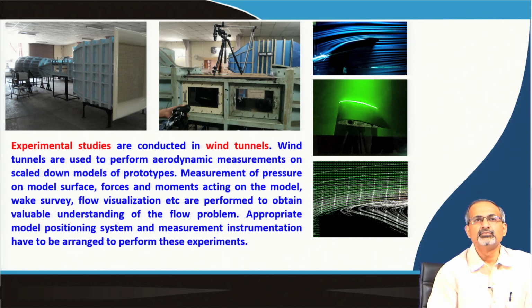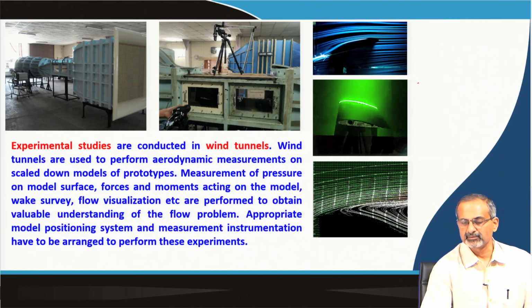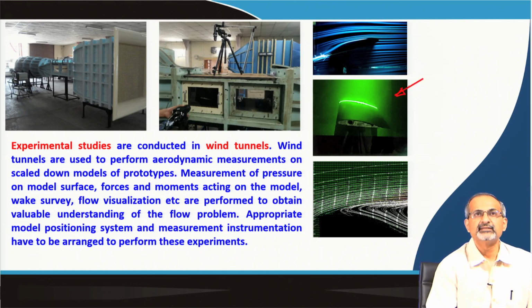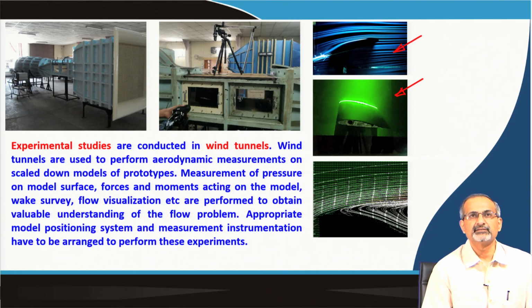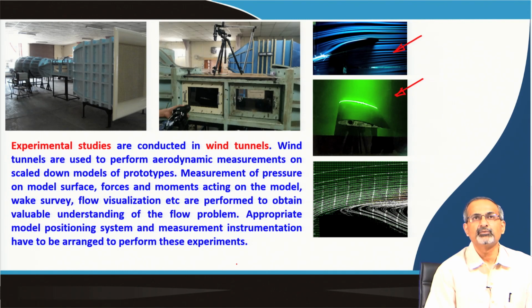So, in the last few modules we have discussed quite a few measurement techniques. Now the point has come where we are talking about a laser based technique, the particle image velocimetry technique. In this wind tunnel we had discussed how a smoke flow visualization, for example, would look like. That gave us very useful qualitative information, but if you want quantitative information, then you have to have a measurement technique like particle image velocimetry, which again is not confined to single point measurement. You can have the measurement done for a particular region of the space, a region of interest to you.